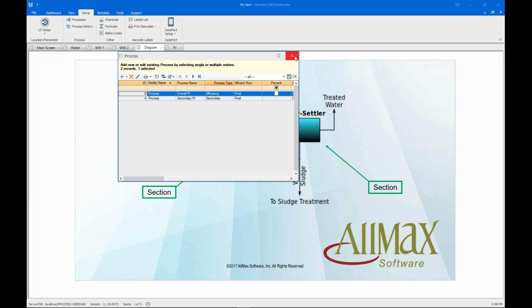One of the things I've done for some clients is set up a limit report with design criteria, not necessarily permit limit information, but design criteria. It'll tell you then in a list, how am I doing? How are my removals? How are my detention times? Based on design of the treatment plant. Again, to give you your overall efficiency of that treatment plant and how it operates.